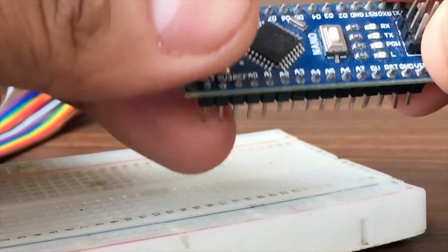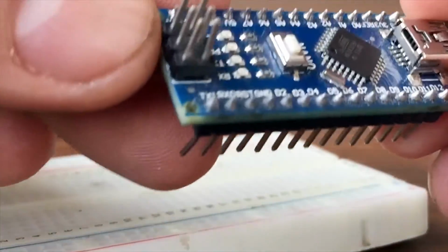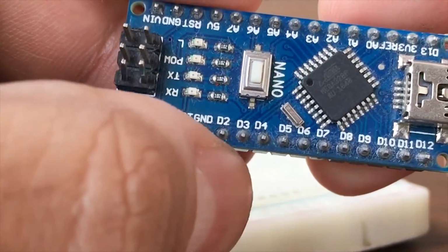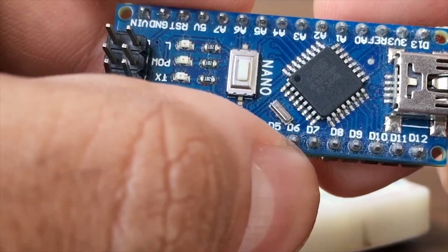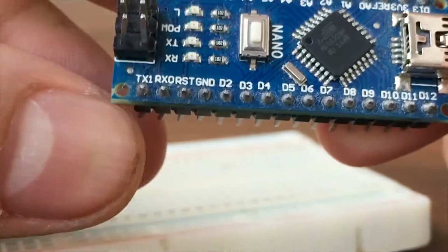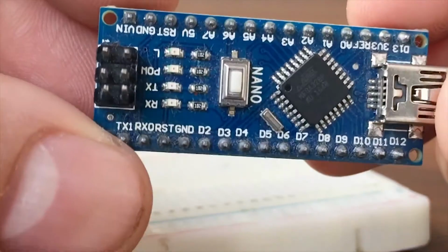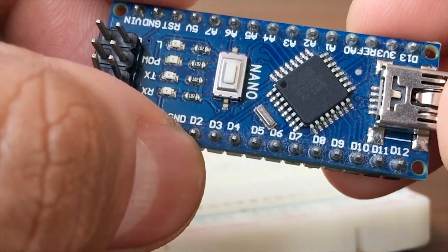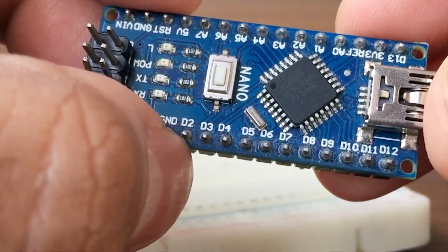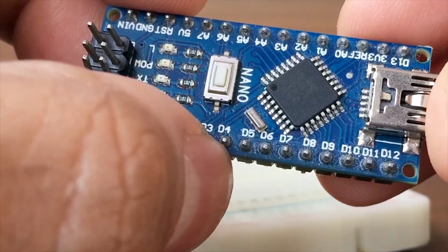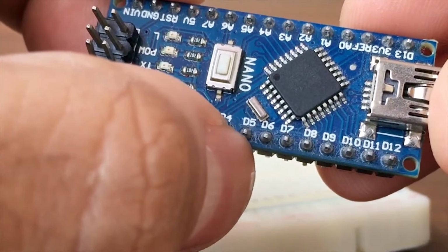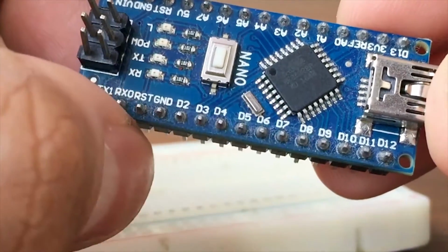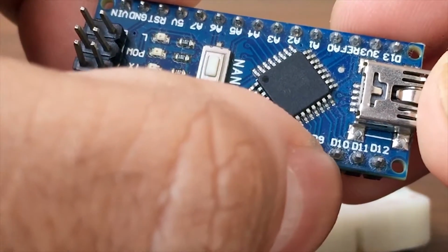So friends, in this Arduino board, as you can see, we have these pins, right? So we have G and D, D2, D3, D4, D5, D6, D7, all through D12. Here we are going to use 8 LED bulbs, so we should need 8 digital pins. So I'm going to use D2, that means our first one, and D3 second, then third, fourth. So fourth one is this one, the D5. So altogether I am going to use from D2 to D9.